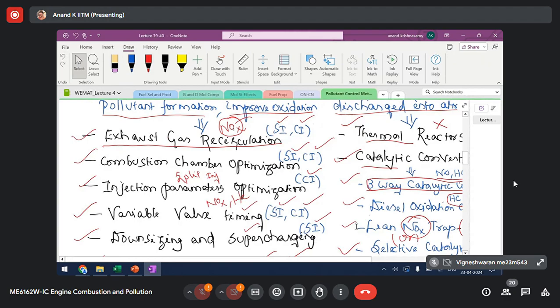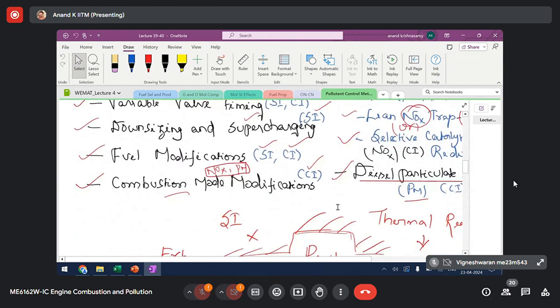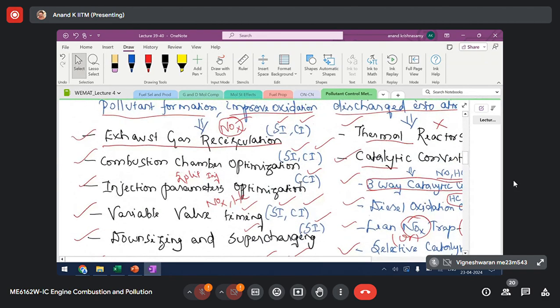So typically, what is the cap? What is the percentage of EGR that is allowed? I said 20%. In a conventional combustion mode, we won't go generally beyond 20%. It will be kept below 20%. Okay, sir. Thank you. But if you are running the engine in alternative combustion mode, you can go above 50%. Okay. I will talk about it as we move on. But in conventional combustion, it's not advisable to go beyond 20% EGR.